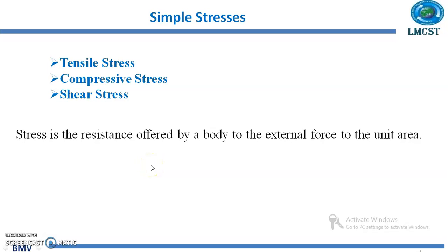In this session, we will see the simple stresses acting on machine elements. We have the simple stresses: one, the tensile stress; then the compressive stress; and the shear stress. Stress is the resistance offered by a body to the external force per unit area.